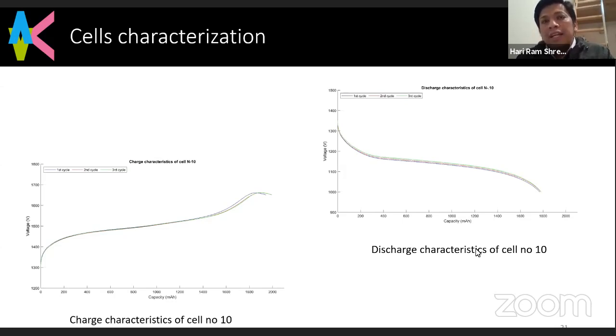If you can get 65.1, it is okay, because all batteries are not exactly similar, but 65.1, 65.2 is okay. Otherwise, larger differences are not good for the connection in series. In parallel is okay, no problem. But in series, it will create high resistance, so the output will not come out properly, and the system will be heated.